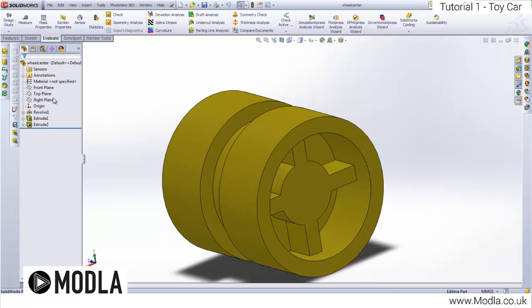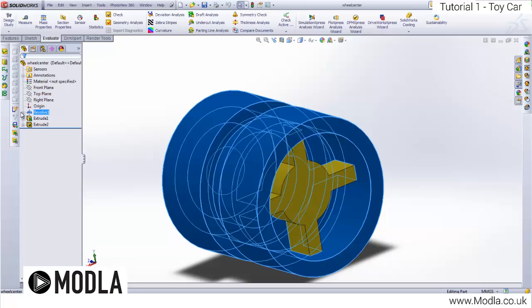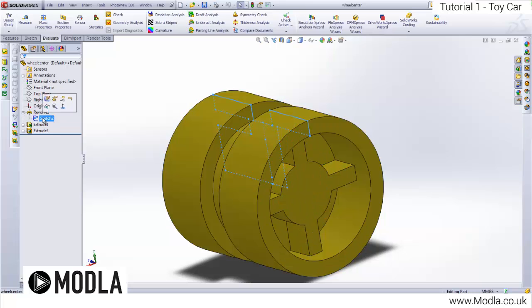So we can see here we're going to use some more tools this time. We're going to use what's called the Revolve tool. The Revolve tool allows us to basically draw a profile and create circular objects. You would create a bottle in this way, a wheel, alloy, and so forth. So we can draw a section view of it and rotate the section view around a central axis.